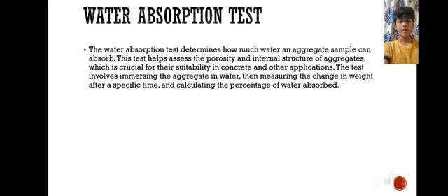Next is the water absorption test. The water absorption test determines how much water an aggregate sample can absorb. This test helps assess the porosity and internal structure of aggregate, which is crucial for stability in concrete and other applications.